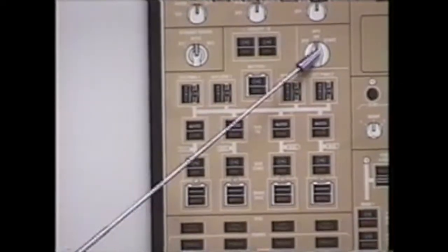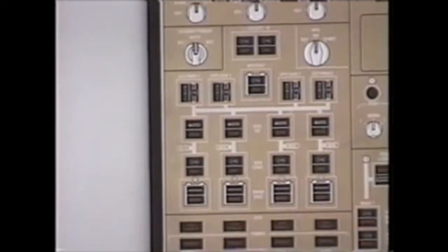In the upper right-hand corner of your electrical control panel is your APU control switch. The APU can be started on the ground. It cannot be started in flight. However, you can take it in the air running. If you take off with the APU running, the APU can give you bleed air up to 15,000 feet. The APU is allowed to run to 20,000 feet as long as you're not in icing conditions.